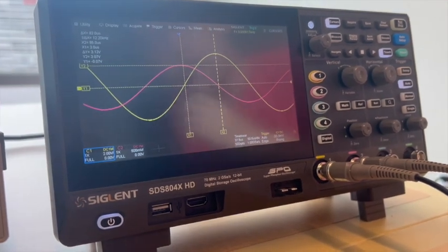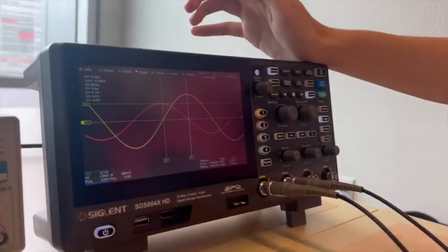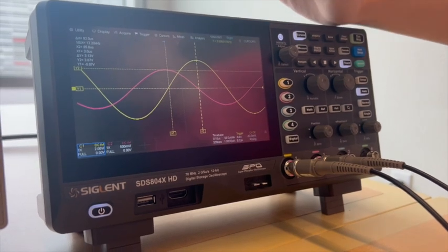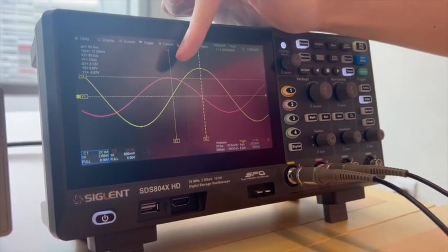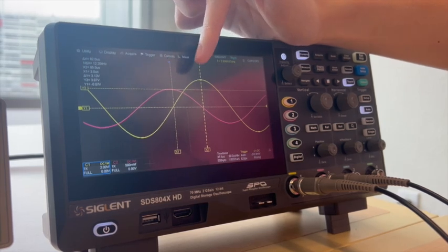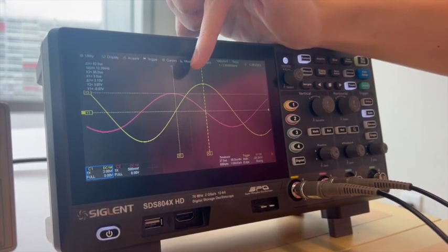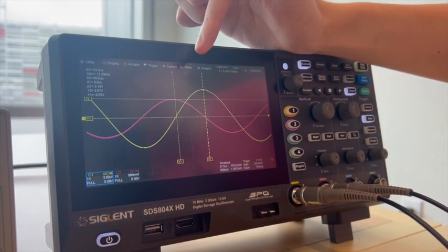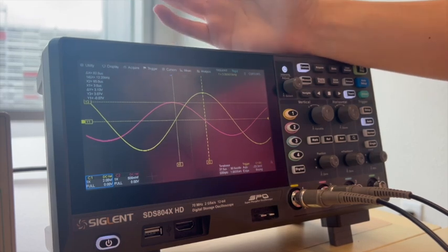Now, the problem is, how do we know if this phase shift is positive or negative? There are different conventions for this, and for the purpose of this lab, we are assuming that if our output signal is coming before our input signal, then our phase shift is positive. That basically means that if our output signal follows our input signal, then we have a negative phase shift. So if we look back here, when we zoom in on only one waveform, we want to look at our signal, right? Here, yellow is our input, while pink is our output. We see that our yellow peak is coming before our pink peak, which means that we are dealing with a positive phase shift. This convention may change depending on who you're talking to. However, it is nice to know which one is leading and which one is trailing.